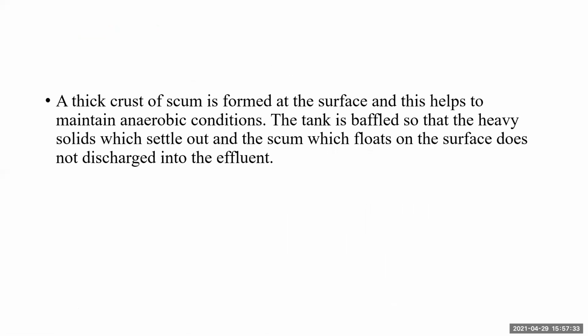When the sewage is held in the septic tank, a thick crust of scum is formed at the surface of the liquid, which helps to maintain anaerobic condition. The septic tank is generally baffled so that heavy solids that have settled out and the scum which floats on the surface do not get discharged along with the effluent.